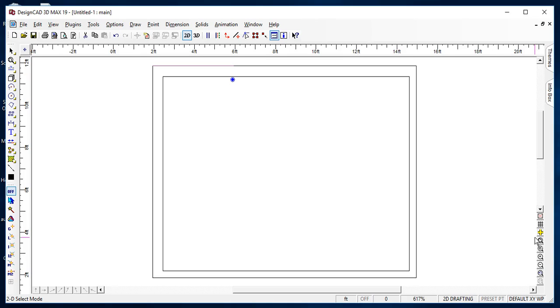Once we have completed this, we can go ahead and show where the windows and the doors are. So we're going to get the ortho line drawing tool, and again I double click on it so it stays up. And I know about here there's a point. So I'm going to right click, go down and right click, press enter.